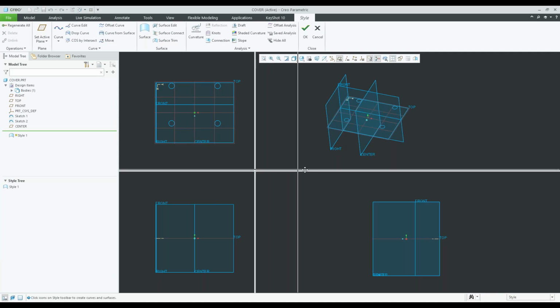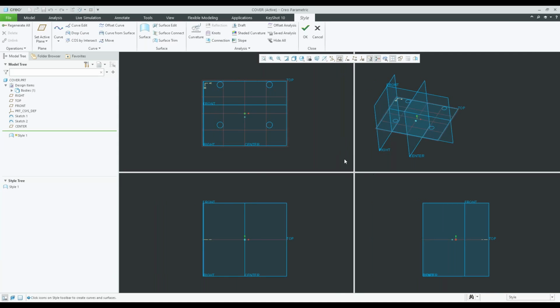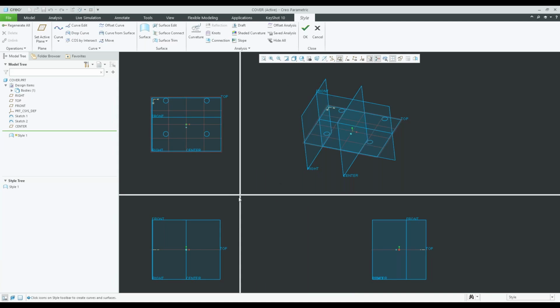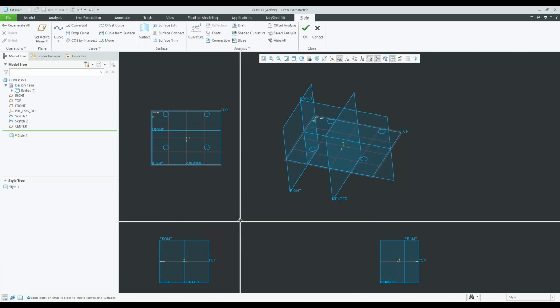And this really helps us see exactly what modifications we're making and the result of those modifications within these different views. So again, I can scale one view. So if I want the isometric view to be scaled up, I can drag the center over and focus more on that quadrant, right?